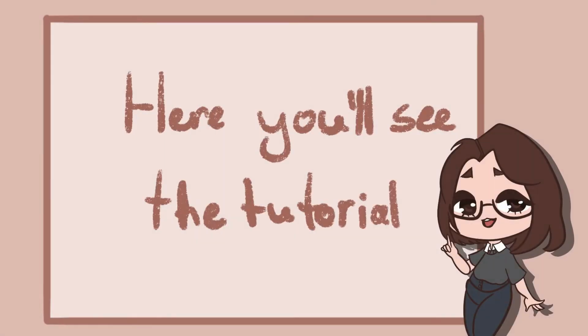Before we start the tutorial, I'm going to tell you the safety precautions when working with the laser machine. First of all, you will need an adult view. When I was working with the laser machine, I had a teacher near me. Second, it is forbidden to leave the machine on without anyone near. Third, it is forbidden to direct the emitter at living beings even if it is de-energized. It is forbidden to use the machine with open access to electronics emitter lenses.